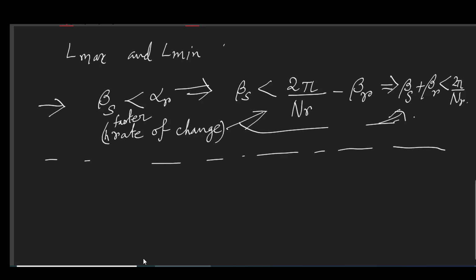Actually, I should write it here. That is why I just drew a separation line so that you do not get confused. Then, another thing that is required: the stator slot angle must be less than the stator pole pitch.